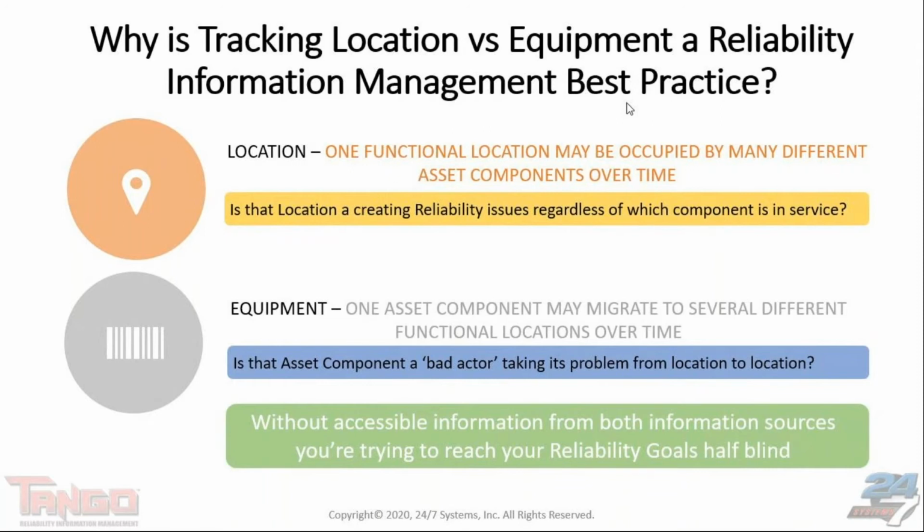And this is actually where most of your condition monitoring activities occur. To do vibration analysis, you don't have to be terribly concerned about which 150 horsepower AC induction motor is sitting on that base plate in service turning that pump. You're doing analysis on the motor that's in that location on the day that you run that vibration route.